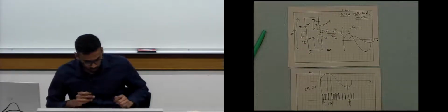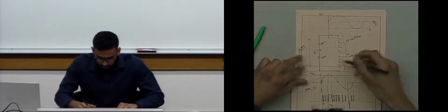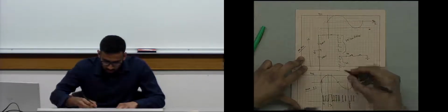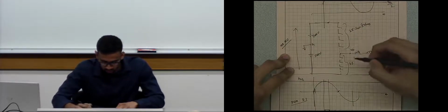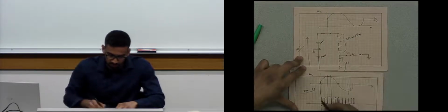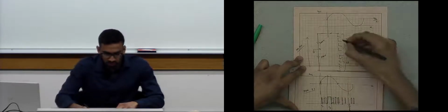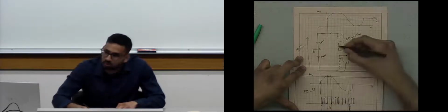Why I was saying this is that if you look at this circuit, to create the same PWM pattern, to connect VDC over 2 at this point, we want all the switches to be on, right? Before it was just S1. Now we need all the 25 switches to go on. During this pulse duration, all 25 switches would have been on, but only for a smaller time during TS. So suppose it has been on for so much time and it wants to turn off, then all the switches should turn off, and they should turn off synchronously.